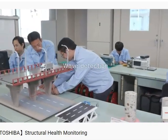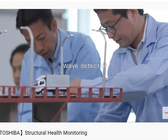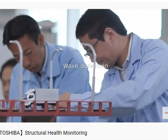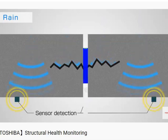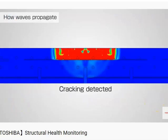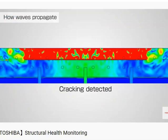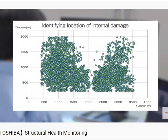This key technology detects elastic waves propagating through a structure. The sensor is highly sensitive. It can even detect the impact of rain striking the road surface. By analyzing the characteristics of propagated waveforms, we can see the degree of the crack inside the structure.